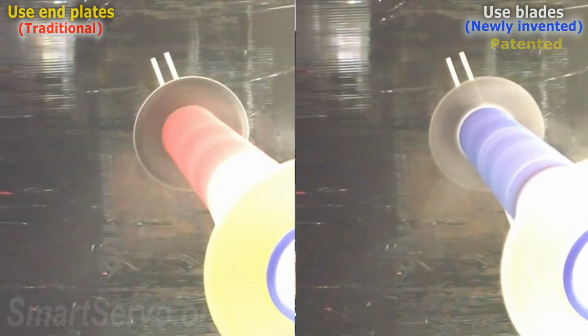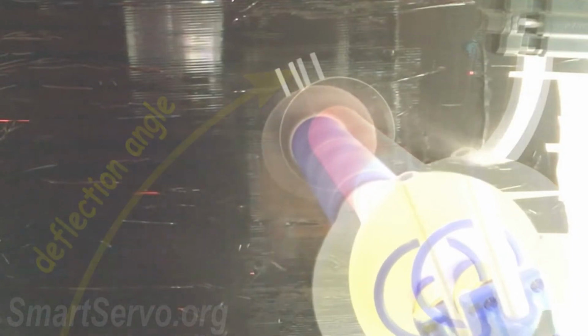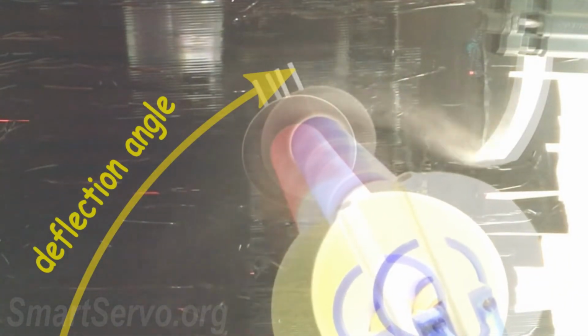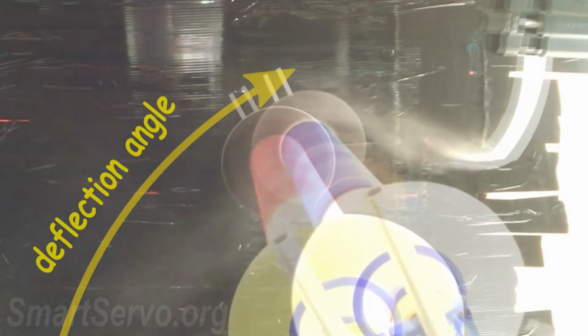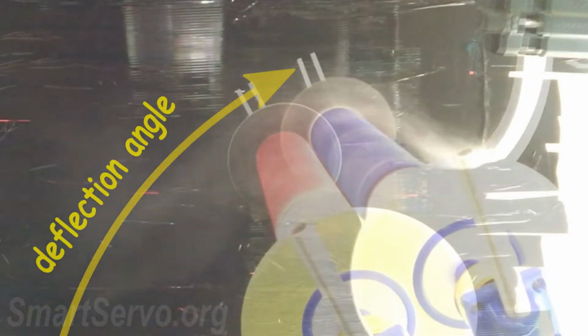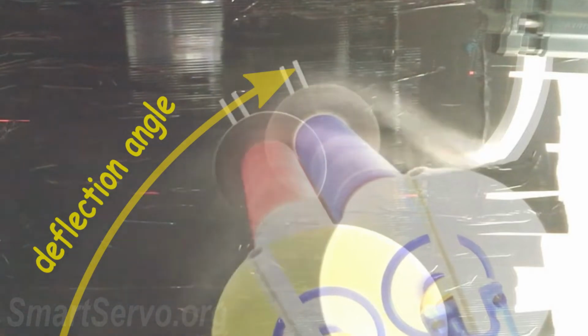View from the bottom. Overlapping two screens makes it easy to compare the deflection angle of each rotor. The closer the rotor is to the smoke blower, the larger the deflection angle and the larger the lift-to-drag ratio. It shows that the blue rotor is closer to the smoke blower than the red rotor. Indicates that the blue rotor has a larger lift-to-drag ratio, which means higher efficiency.